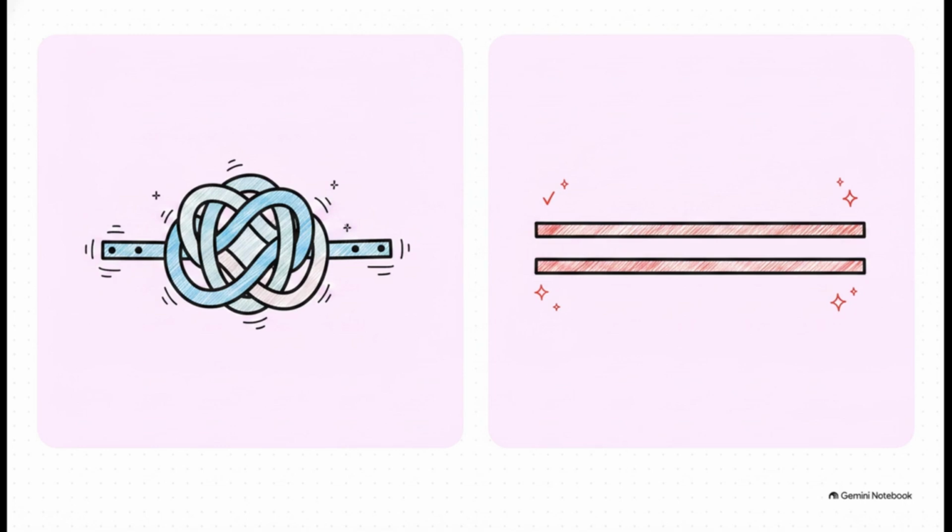The ABC reference frame. In an induction machine, your stator and rotor flux linkages depend entirely on the rotor angle. Why? Well, because the mutual inductances between the windings are position dependent. They're constantly changing as the rotor spins. So you're dealing with time-varying sine waves and highly nonlinear equations. Honestly, it's a stability nightmare.